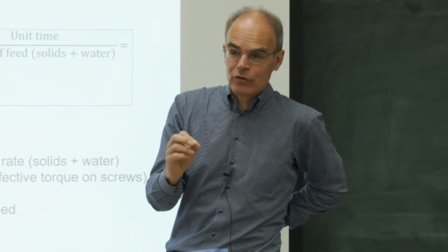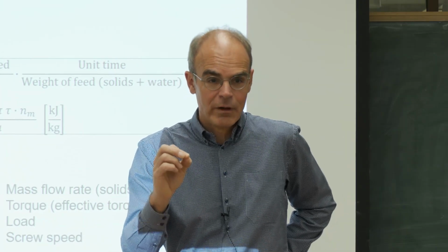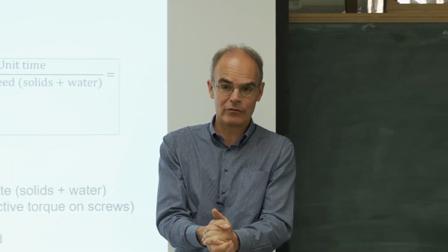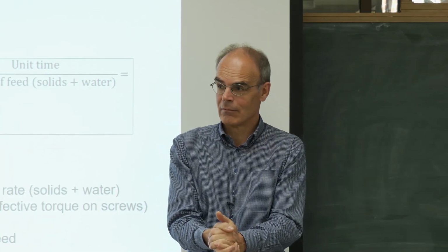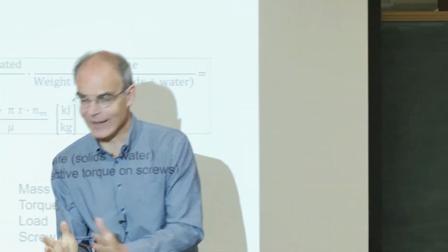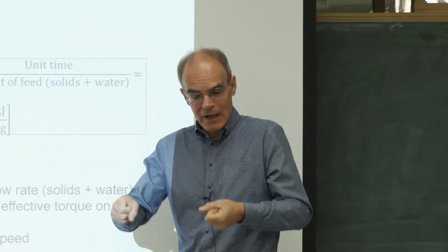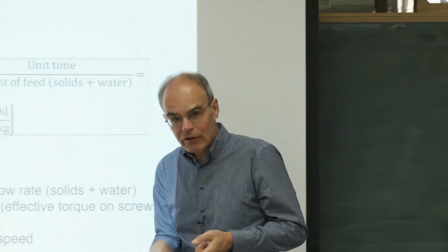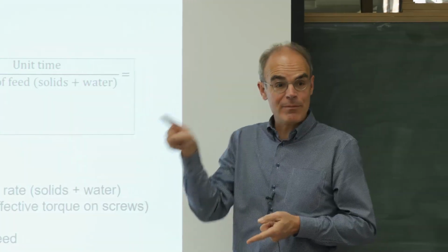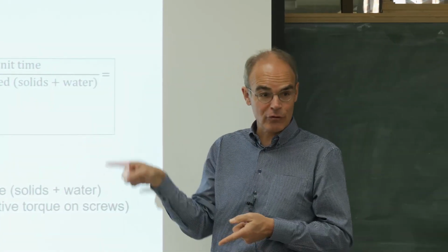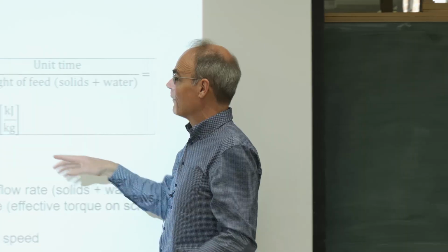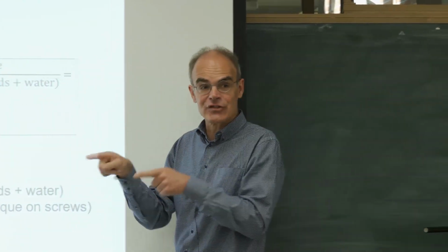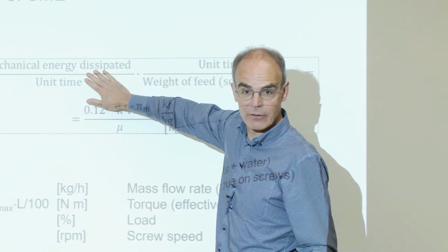If I have a very high viscosity material, does it take a lot of effort to turn these screws, or is it easier to turn them? Higher. If I have really very pasty material, I need to exert more effort to turn those screws. As a consequence, if I turn these screws in the same manner, I'm actually dissipating more energy. I need more force to turn those screws. Yeah? So over that rotation of the screws, I'm dissipating mechanical energy in the material.